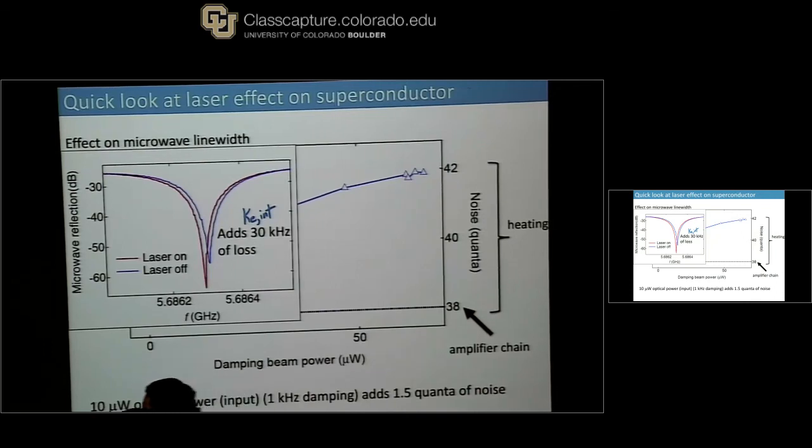how you measure the noise? Yeah. So in this particular case, for example, you can see that we're looking on top of some amplifier noise that we calibrate ultimately by calibrating temperatures in the microwave system. In the optical system, we basically calibrate to shot noise, right? So we know very well where shot noise is, and then we find things on top of that, and it's not a trivial process.